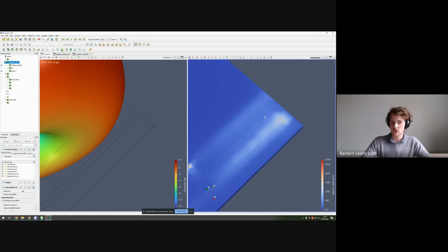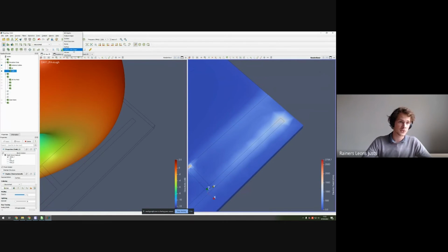If you want to see how the mesh looks inside ParaView, you can enable the visualization by selecting the object you want to validate the mesh on. In this case, it'll be the solid one, which is the substrate. You will have to click on the electric field distribution window here, which has a blue outline on the outside, and then select surface with edges on the top.